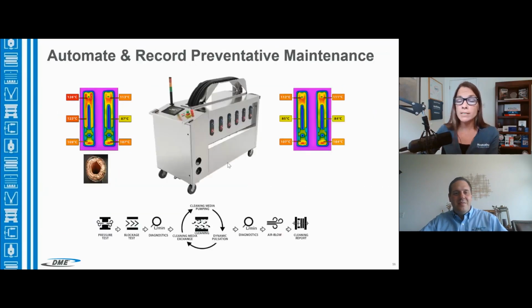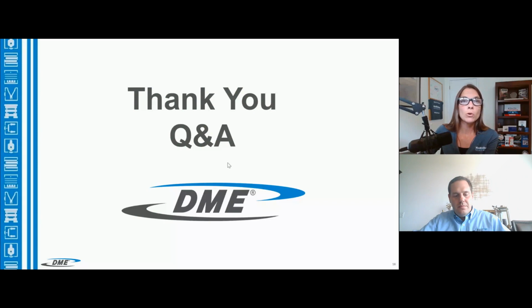Am I correct that a conformal cooling area in my tool may over time become a hot spot? So, anything can happen, but typically the conformally cooled water circuits are smaller. And then every time you go around a bend, you have a chance of sediment sticking to the non-contact areas and really creating a buildup. But yeah, conformal inserts are notorious for plugging up.